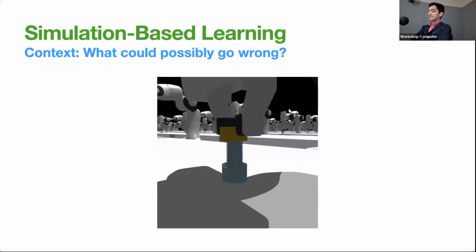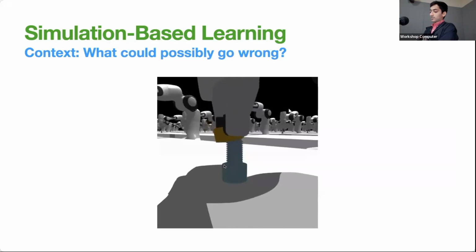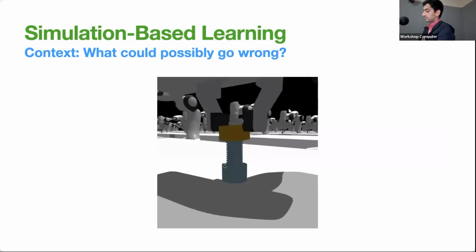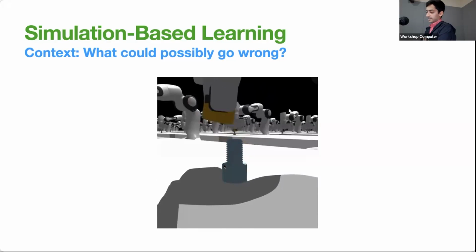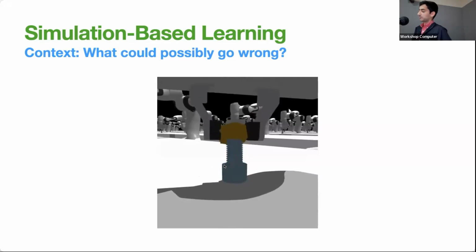Of the 3 subtasks, the screw subtask was by far the most challenging to train. Threading a nut onto a bolt is so natural for us as humans that it may be difficult to understand why a virtual robot trained with RL would actually struggle with it. So here's what our initial results look like. There were sudden collisions between the nut and the bolt, misalignment of the nut when engaging the bolt threads, jamming of the nut during tightening, and precession of the gripper around the bolt.